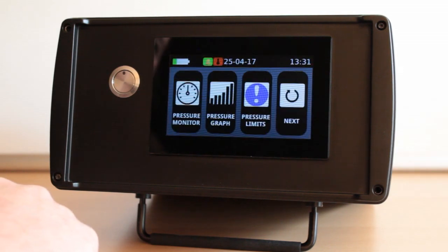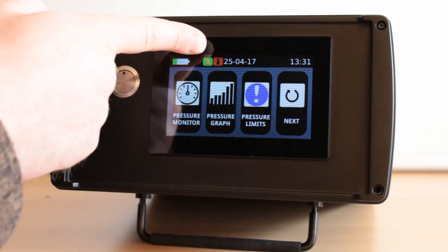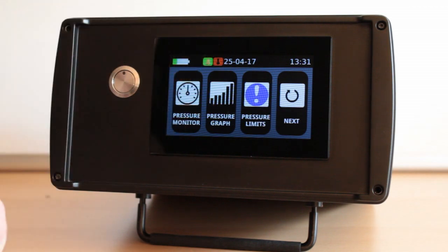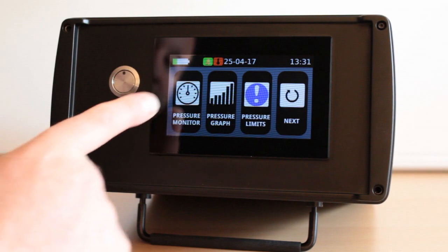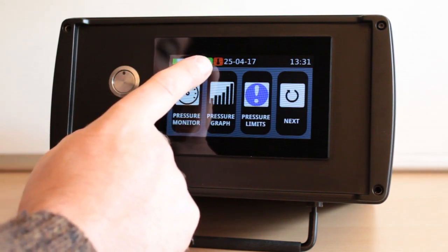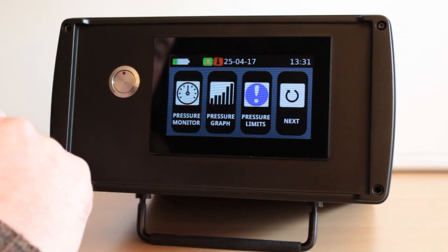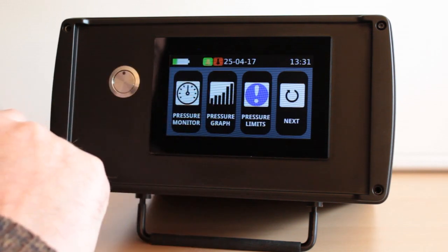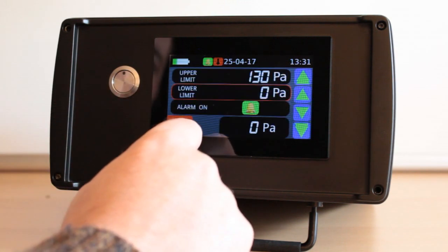Now if you listen for the relay clicking when I acknowledge, okay, what that would do is cancel the external alarm, but you can see here there's another little icon come up to say that you've breached the lower limit. Even just momentarily it will trip. The sensitivity of that could be increased or decreased, I guess. To vanish that, you need to return the pressure to normal. At the moment there's still a relay held in to keep your air mover running.